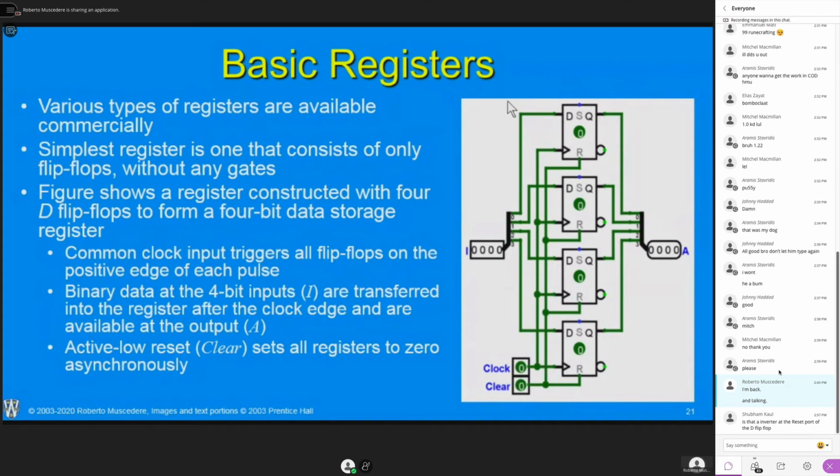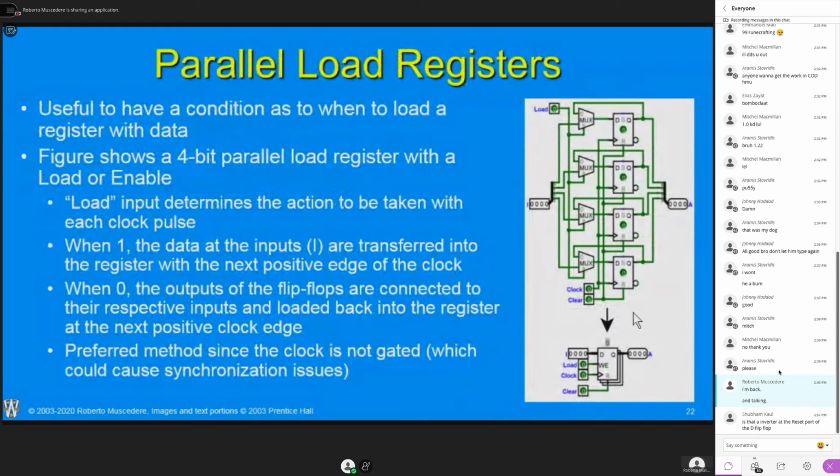Now, again, it could be quite tedious building these things manually all the time. So again, fortunately, Logisim has a way of doing this for us. We can put in a 4-bit register here. It has an element in its library for us. And with that, it has a write enable line. It has a reset line. No clear line, or sorry, a set line, but again, it's rare that we do that. It's not saying that we couldn't, but this is a common part.